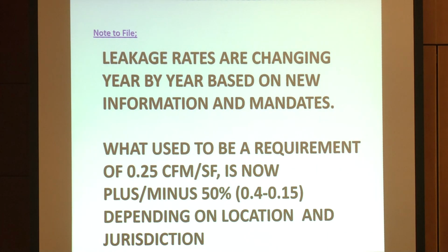And it has to pass, right? That's wild for residential buildings, but they're taking it very seriously, because obviously if the building leaks, all of your cooling or your heating is going out the window or out the door. So it makes good sense for energy efficiency to make sure that the building is tight and doesn't leak. It's really good.